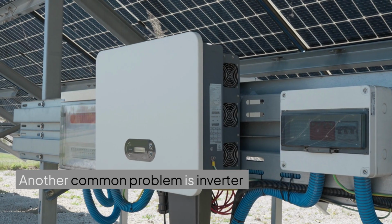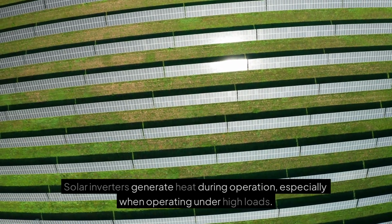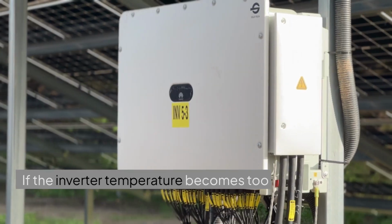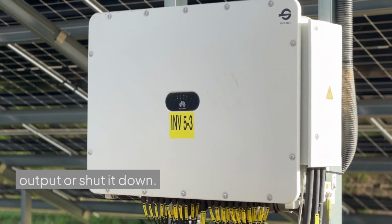3. Over temperature fault. Another common problem is inverter overheating. Solar inverters generate heat during operation, especially when operating under high loads. If the inverter temperature becomes too high, its protection system may reduce output or shut it down.